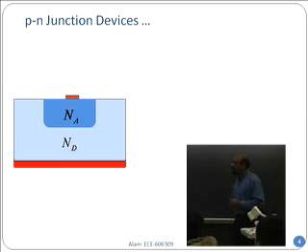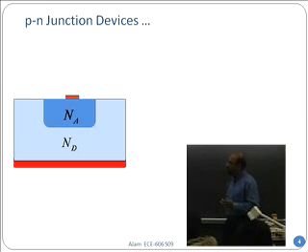And the top red and the bottom red, these are contacts. For now, we will not worry about these; they are generally metal contacts or various types of highly doped silicon contacts. We will come back to this point a little bit later. It's actually a very important problem. We'll come back maybe five or six lectures down to the junction between red and blue. These are called Schottky barriers. We'll come back to that.